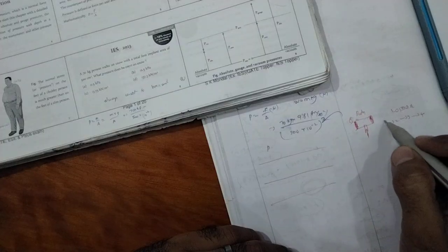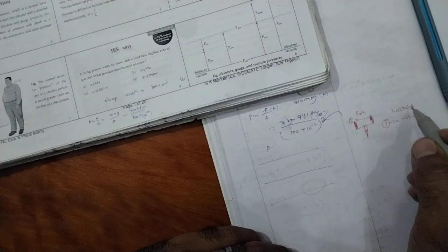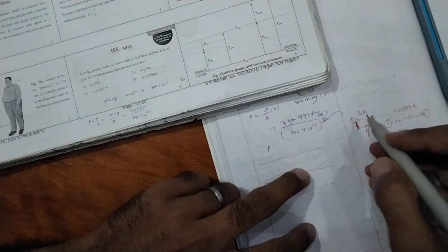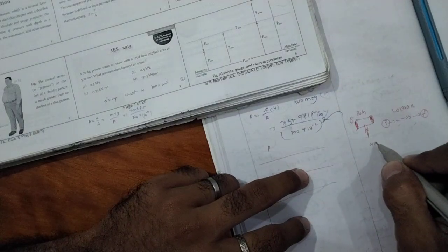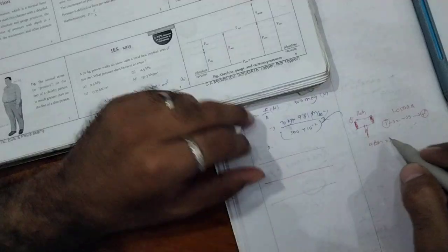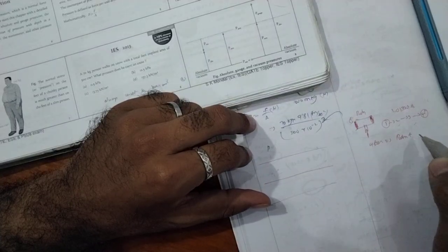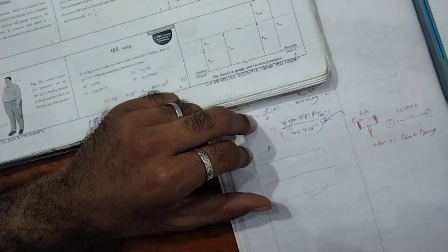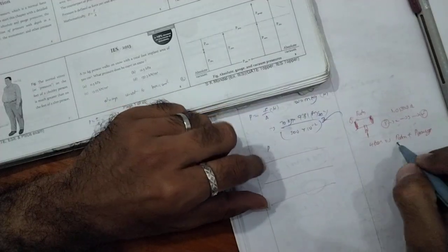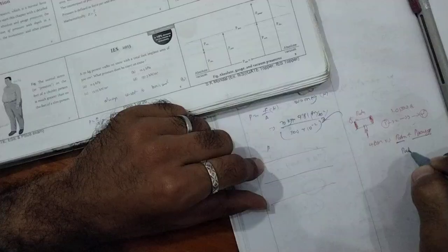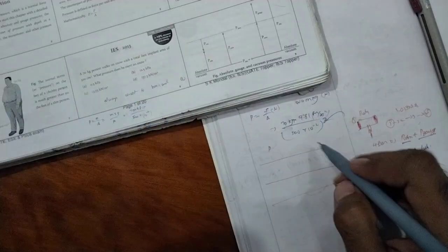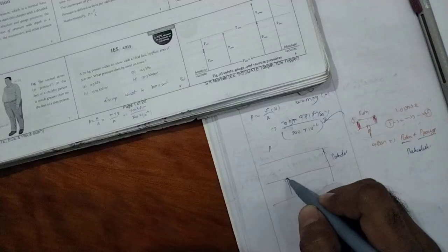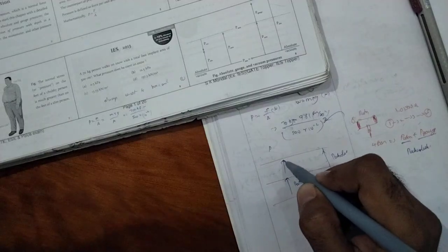At the initial stage, how much does it have? It has 1.013 bar. Later on it goes up to 4 bar. So what will be the total pressure? You can see the total pressure is 4.4 bar. So it is a combination of P atmospheric pressure plus P gauge pressure. Okay, I think you are getting the point. That combination, P atmosphere plus P gauge pressure, is called P absolute pressure. So this entire thing is P absolute, this part is P ATM, and this part is P gauge pressure.